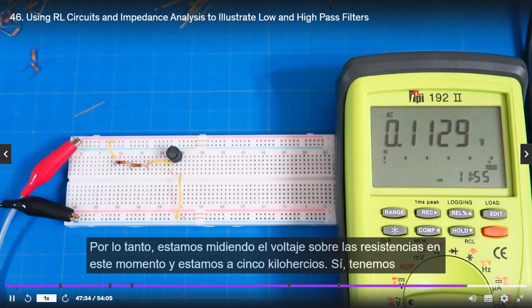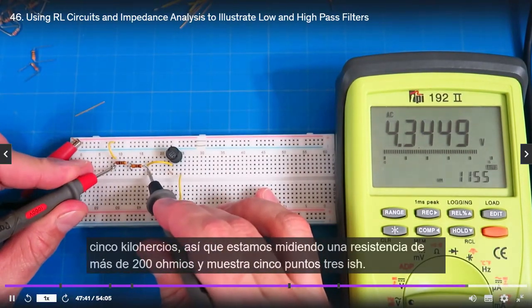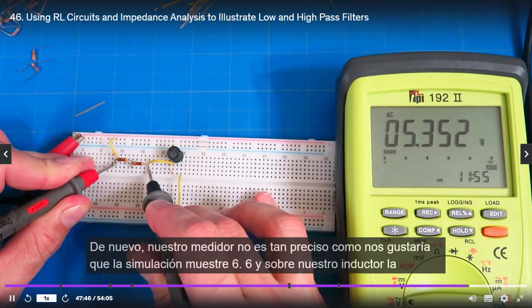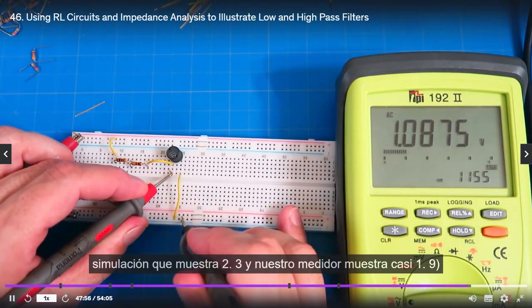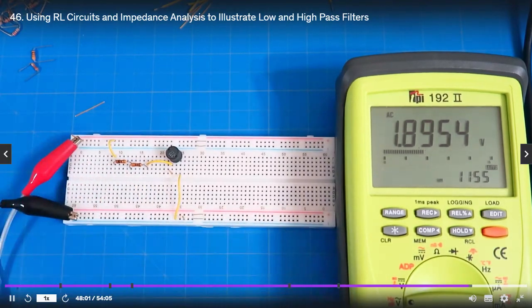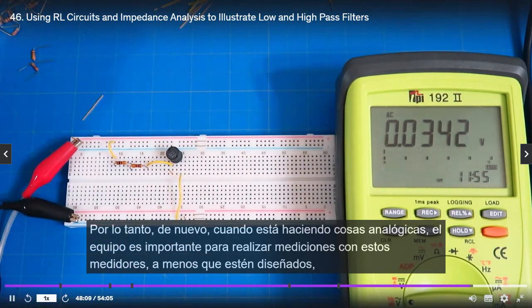So I'm measuring the voltage over the resistor right now, and we're at 5 kilohertz. Yep, we're at 5 kilohertz, so we're measuring over our 200 ohm resistor, and it's showing 5.3-ish. All right, again, our meter is not as accurate as we would like. The simulation is showing 6.6. And over our inductor, the simulation is showing 2.3, and our meter is showing almost 2, 1.9. All right, so again, when you're doing analog stuff, the equipment you're making measurements with is important.